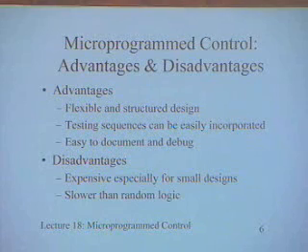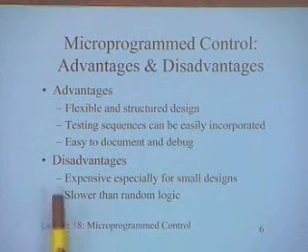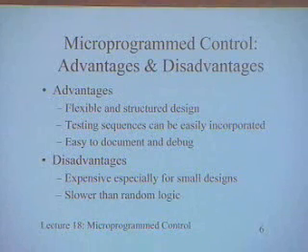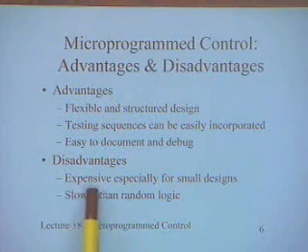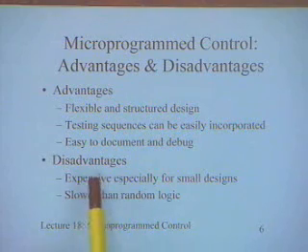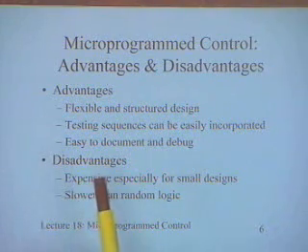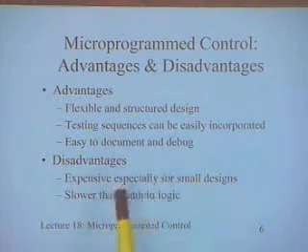But then it's not always that one adopts microprogrammed control, and the reason why one doesn't always adopt it is these two. When it comes to small systems, it's very clear that microprogramming is more expensive. When it comes to larger systems, it can go either way. Microprogramming could be more expensive, or sometimes it could be cheaper also. Because there is an additional ROM involved, there is a sequencer involved, all of which actually get integrated in a random logic design. Here they are all separate.